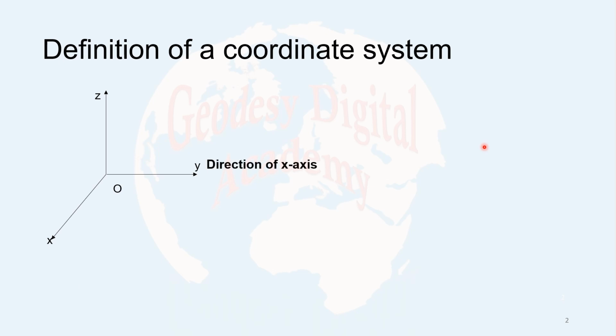The x-axis is more conventional because the Earth is rotational, and we can select any meridian actually and consider it as reference. In our time for the terrestrial coordinate systems, we use the Greenwich meridian. Greenwich is the name of an observatory close to London. And also for the celestial coordinate systems that we apply in geodesy, we can consider the vernal equinox, which is the point which is constant in space. We can consider that one too.